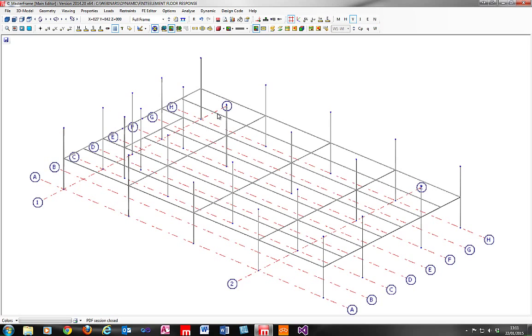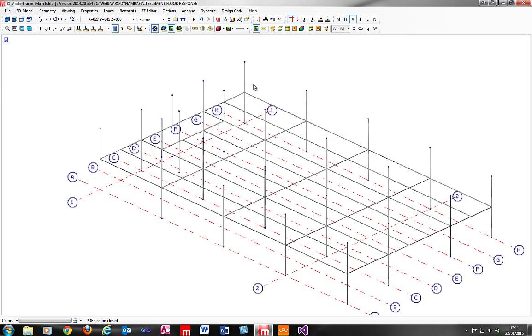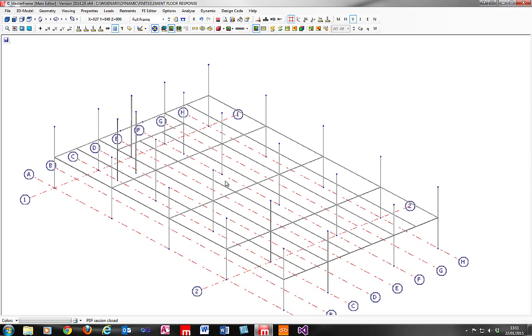Typically, obviously, any permanent loading or dead loading, as it would be referred to in the BS 5950 terminology, would be fully included in the mass, but there's also a recommendation that one would consider including up to 10% of the live load in the mass contribution.